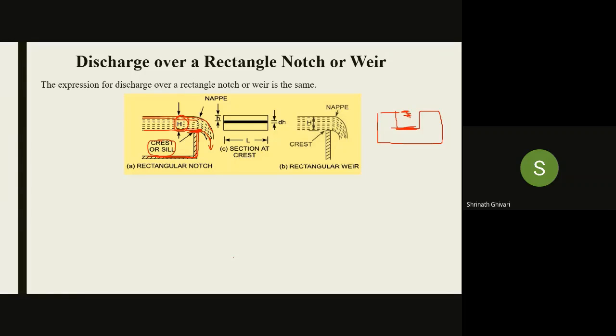Suppose this is a tank, there is a tank behind this, and I've connected this open channel to it. I have filled the water using the valve. The water is filling this, and it is falling from here, so I can measure the rate of flow from here. Now my question is, if I partially open the valve, now it is fully open, what will happen to H? Will it reduce or increase? Capital H? Reduce, because the flow rate of water will be reduced, right?